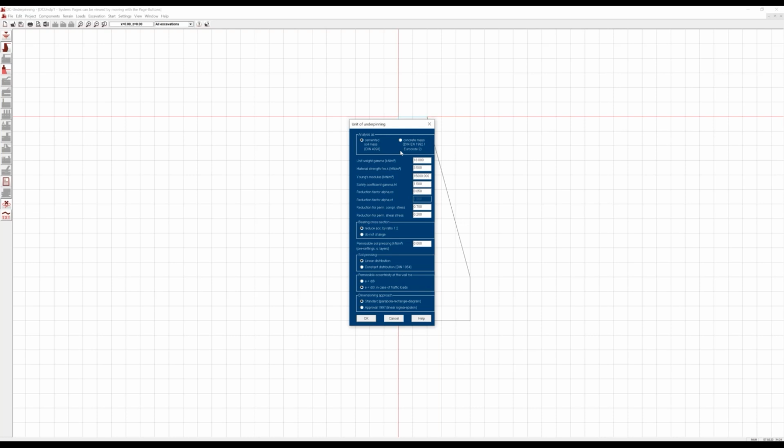This is quite similar, but depending on the material strength, fMk, we have different reduction factors and different safety factors if we change here the type of standard. So this is a little different use of the factor to be used for the design of the non-reinforced concrete.